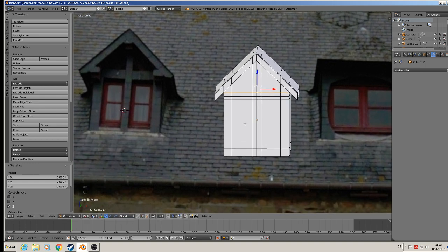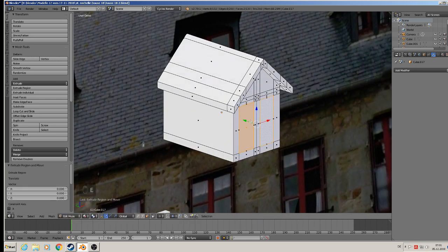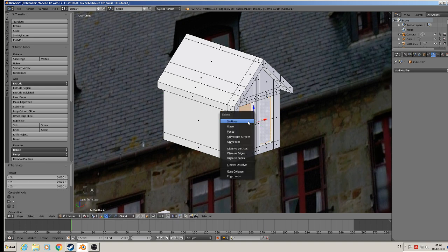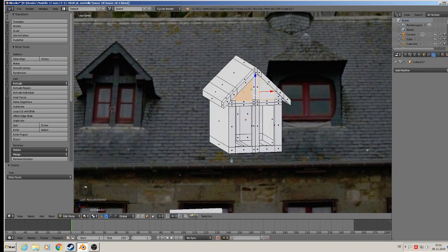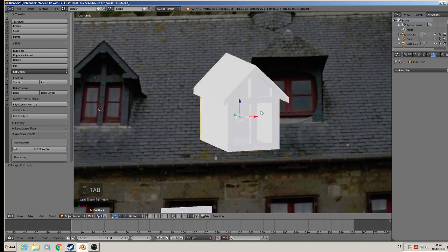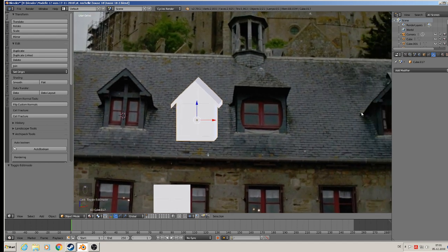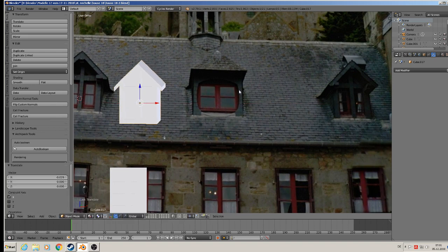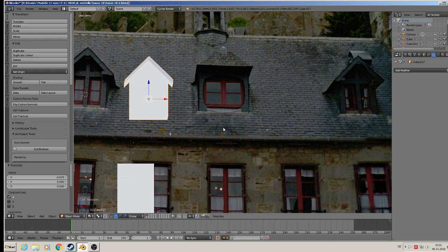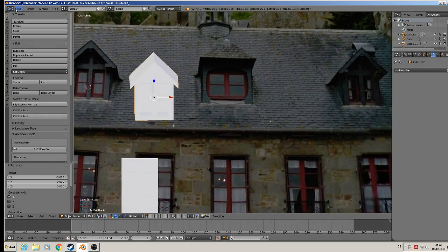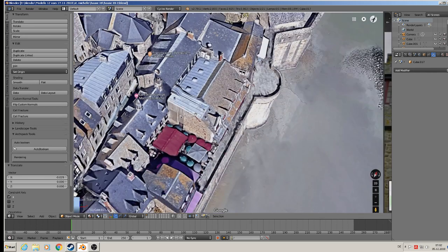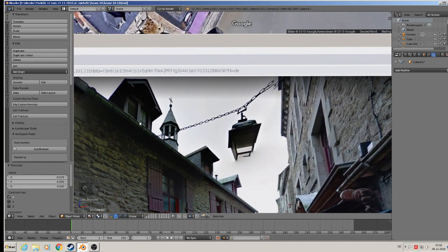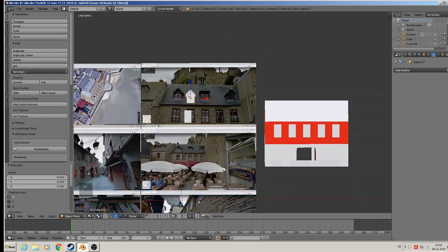Good. The windows should be cut in, but now we can simply plug them in. So we extrude and bring them in, and then X delete only faces, and let's open up. Here we have to go deeper too, so extrude and bring them along Y. Good. So that is one of the 3, and this one is a little different. You see that. File, save. I must view from the top, but it is the same style there, that is good. And here, that is the same style as at the other part there, that is good too.